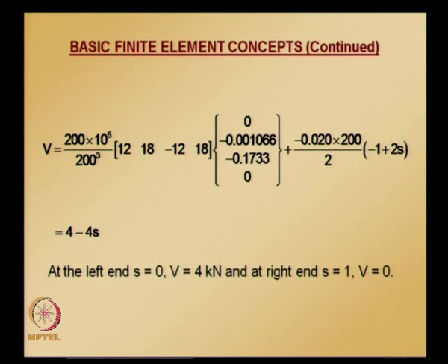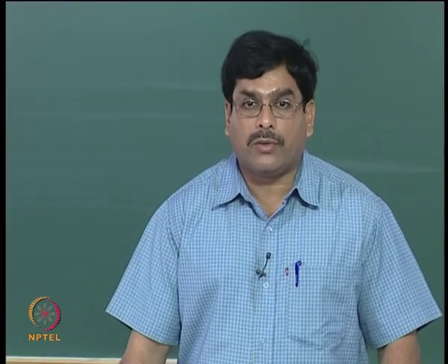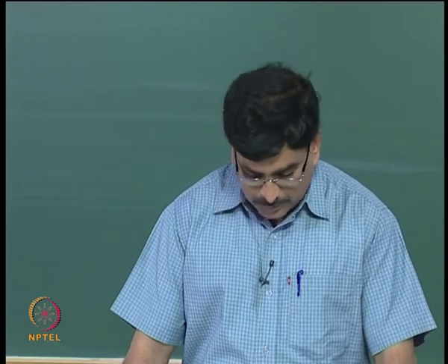So, now we have the element 1 solution and the element 2 solution, and at any point inside element 1 or element 2, if somebody is interested in finding the moment and shear, we can substitute the corresponding S value and get the moment and shear at any point in either of these two elements. So, with this information we can plot bending moment and shear force diagrams.